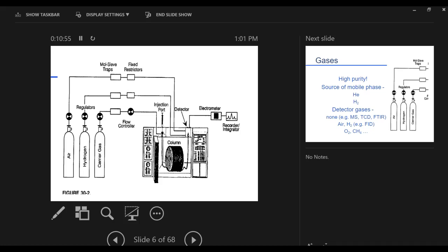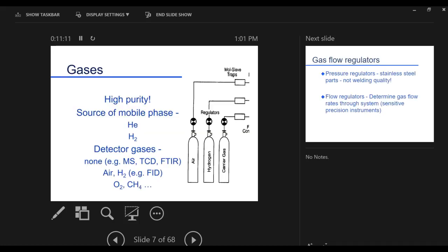The more analyte we burn, the greater the electrical current. So what we're doing is measuring electrical current across the flame. As long as there's something there that carries current, the more is there, the more current. So we get a response, we get a peak coming out of the system. That's the most common detector, a flame detector.